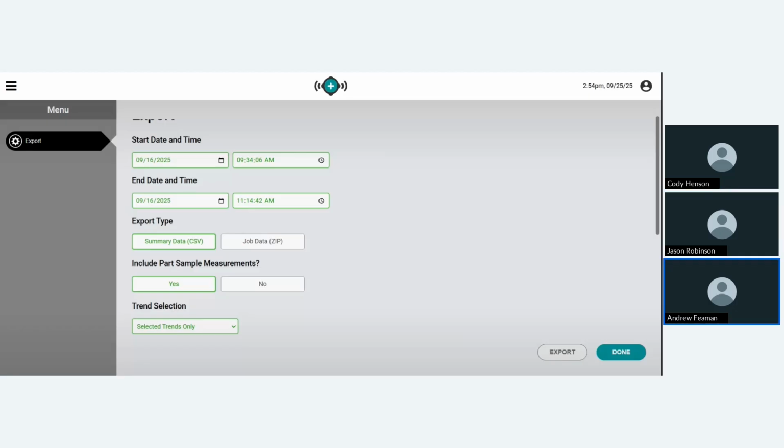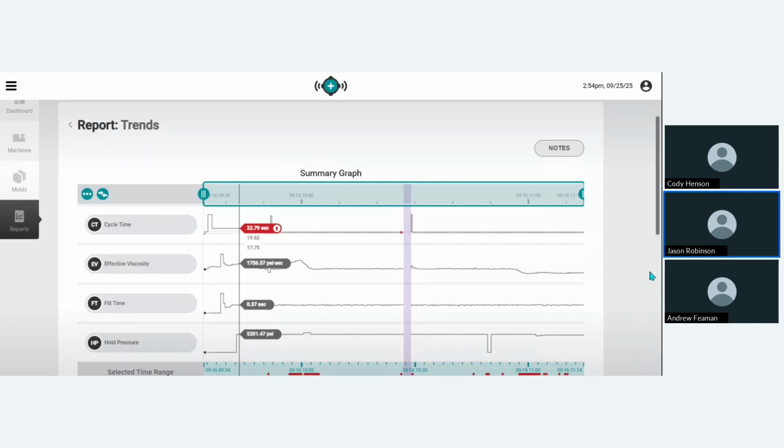So if I have a plus or minus reject window of 2 seconds, I could put my warning at plus or minus 0.5 seconds, which would then at least give me a data log that, hey man, somebody changed this within its allowed control limits. Yes, that's a good use of it.